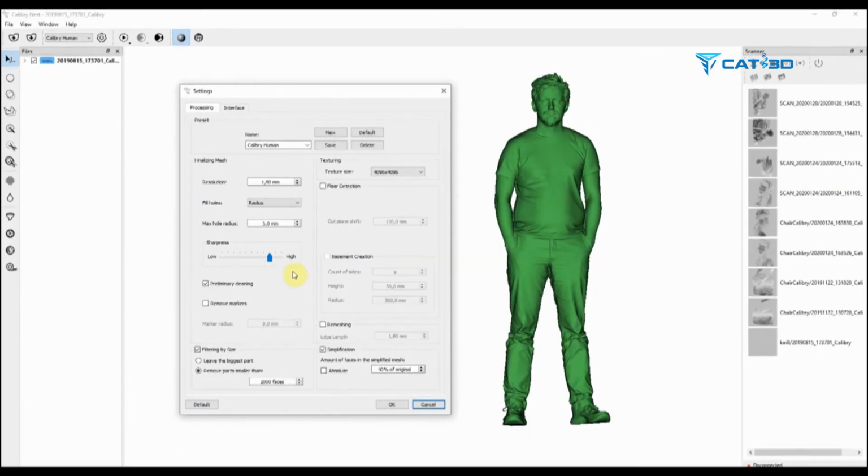All our scanners are optical. They project a light grid onto objects. And if you dial the sharpness setting to the left, the light grid in the areas where data is lacking will be less distinct. But overall, you can experiment with this setting. On average, we keep that setting somewhere in the middle. A lot of people never change this setting because the effect it has on the model isn't really that significant.